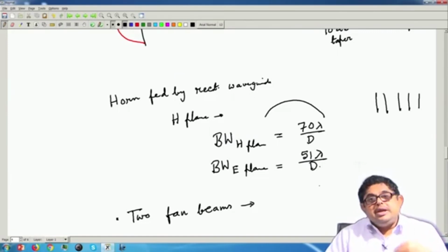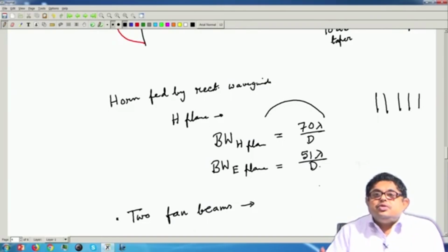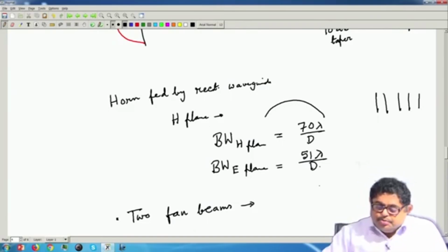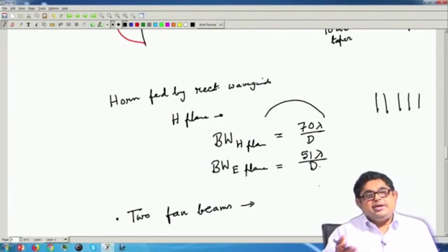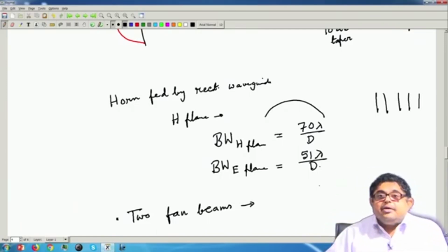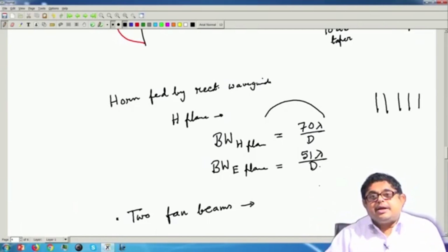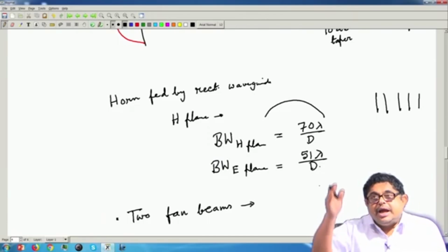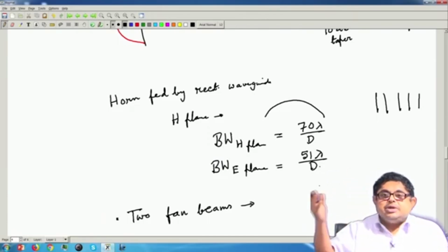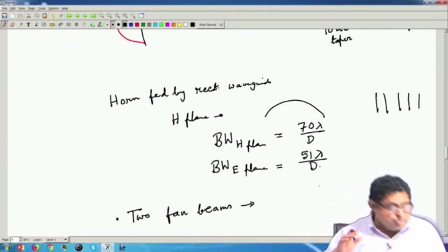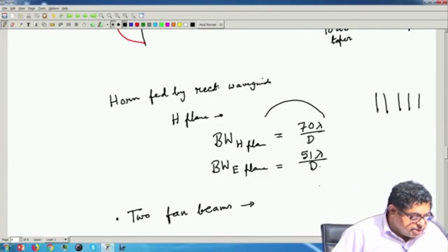So, in the elevation plane it does not need a narrow beam; it will have a narrow azimuth fan beam, and it can detect. Whereas in the case of aircraft you cannot do that, because aircraft can be at various azimuths and various elevations. So, you need two fan beams for these.